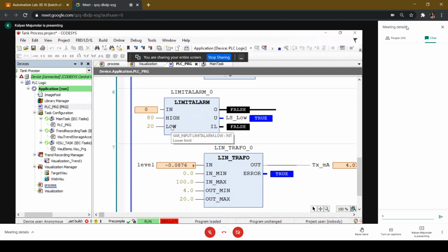When the liquid level crosses the lower sensor, the output is 1. Similarly, when the liquid level is below the upper sensor, the output of the sensor is 0. When the liquid level crosses the upper sensor, the level is 1. So you basically have two sensors.